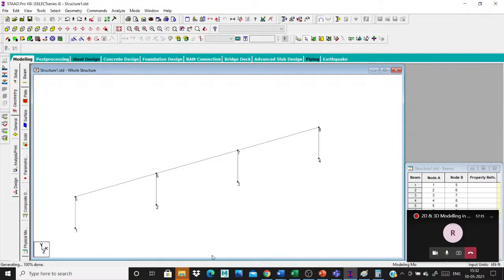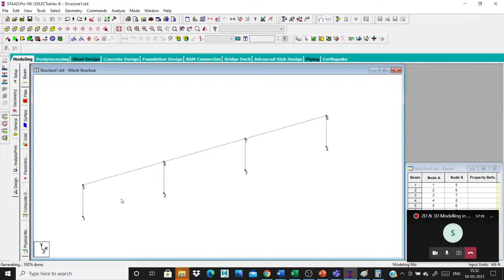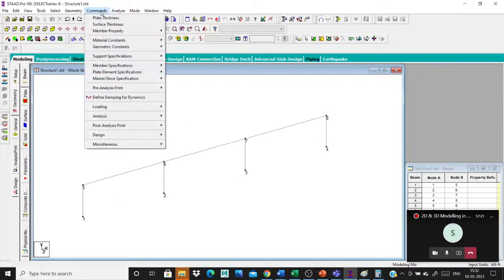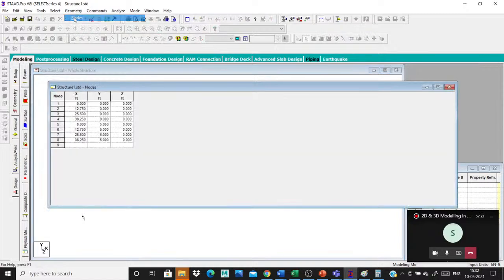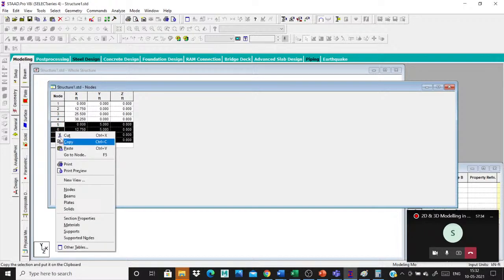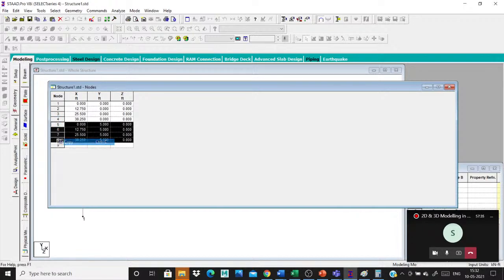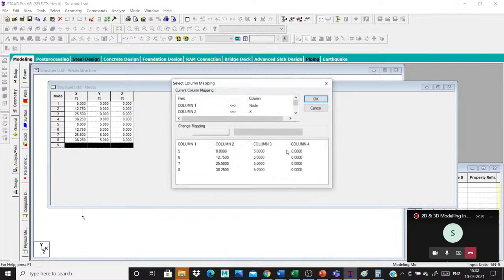Okay, it created some problems in the geometry node method. You can simply go for another method also. Go to geometry, node method, the same typing method as for this geometry method. It is already created like 5 meter, 5 meter. I will create another node. Simply select this, then copy and paste it. Then for this column size, simply go to a total of 8 meter.